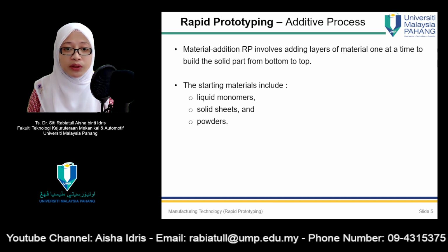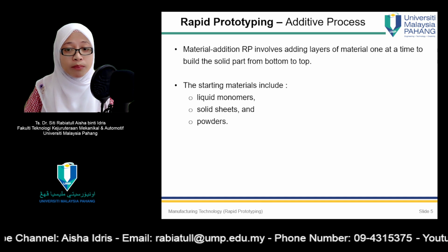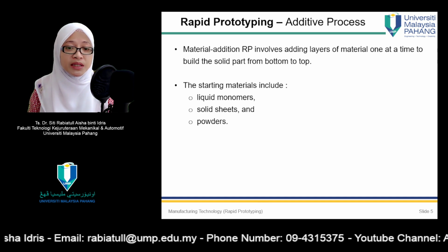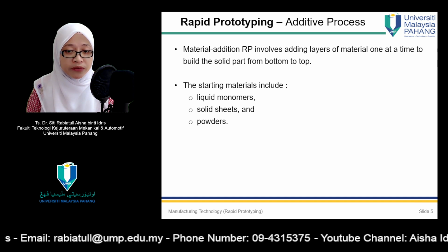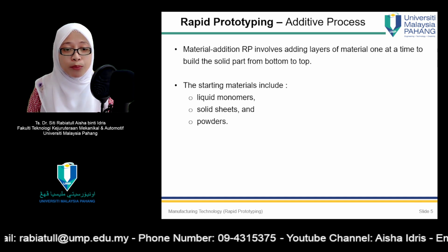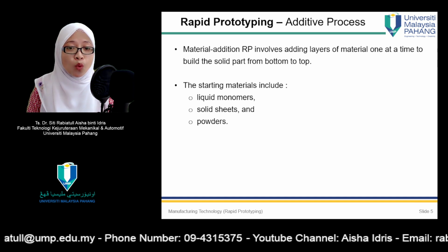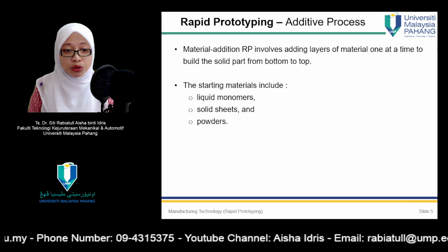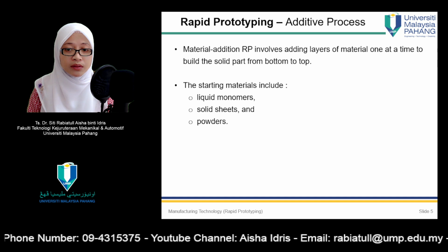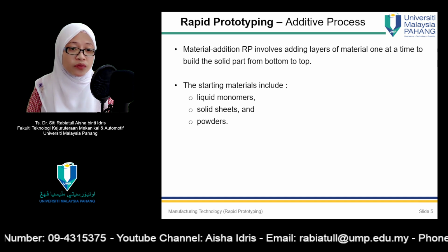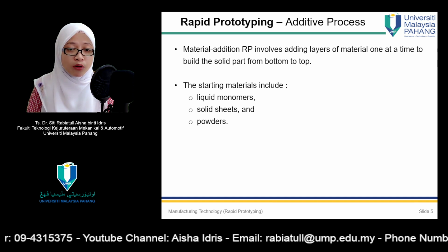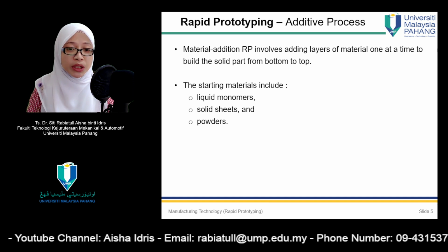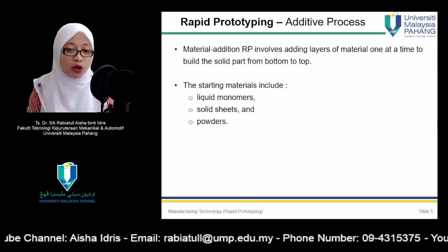The starting material is often a solid block of wax, which is very easy to machine, and the part and chips can be melted and re-solidified for reuse when the current prototype is no longer needed. Other starting materials can also be used, such as wood, plastics, or metals. The CNC machines used for rapid prototyping are often small, and the terms desktop milling or desktop machining are sometimes used for this technology.